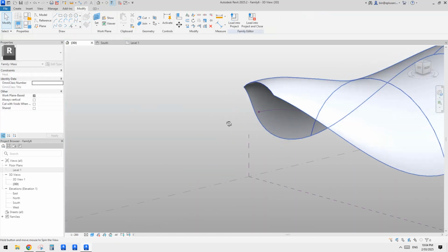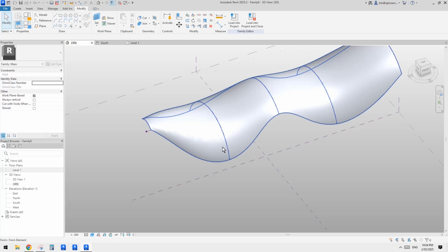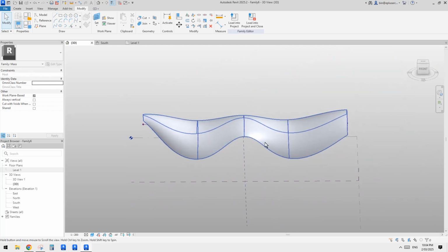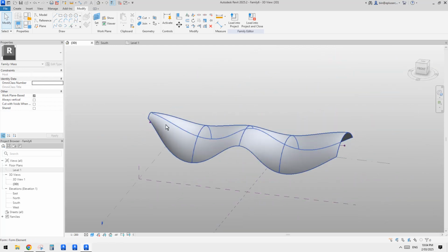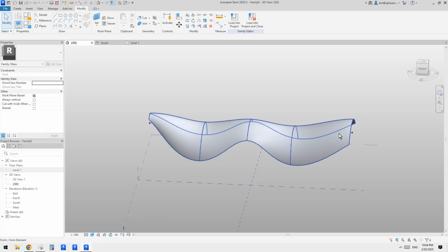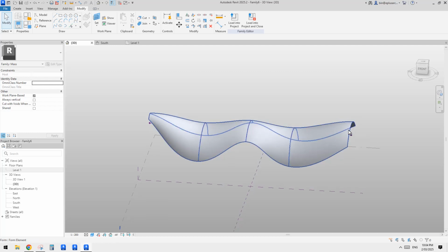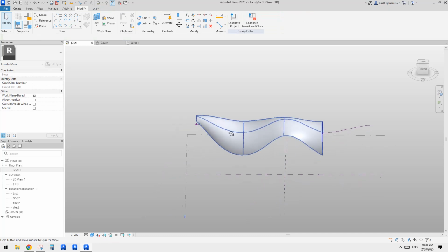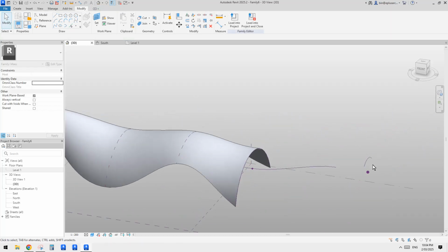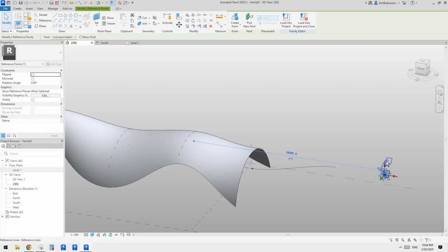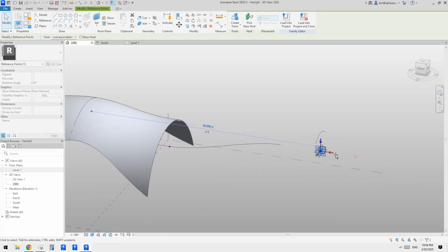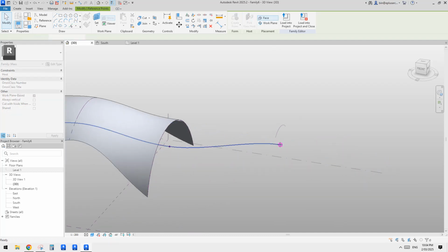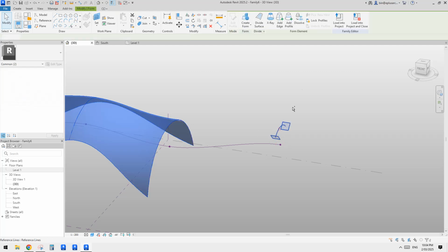Okay, something like that. Yeah, so that's good. Then this, maybe we're trying to copy this one, right? So maybe we can delete this one. Don't need this point. We can copy everything here to here. Select this. Just make sure that the reference line, the profile is still on this point. Pick new host, and we can select the surface and select Control select this and create.